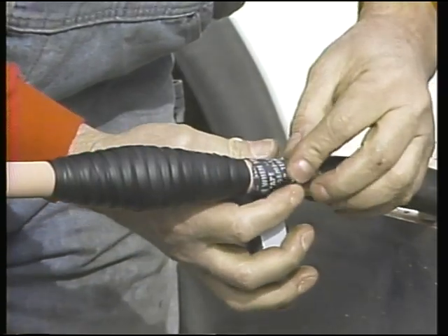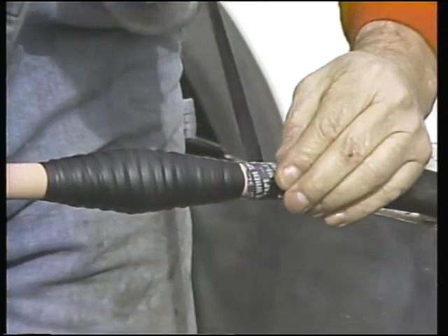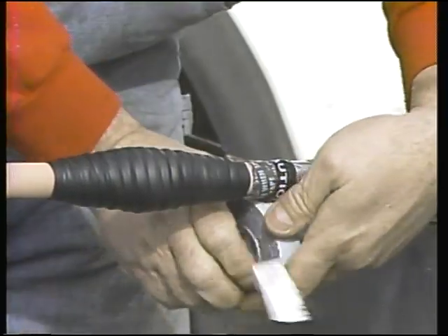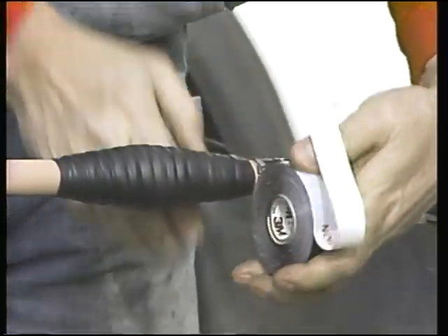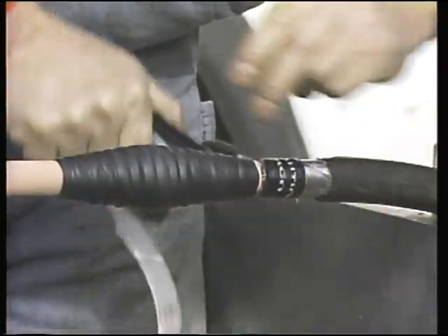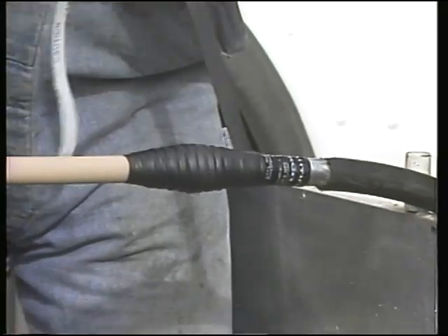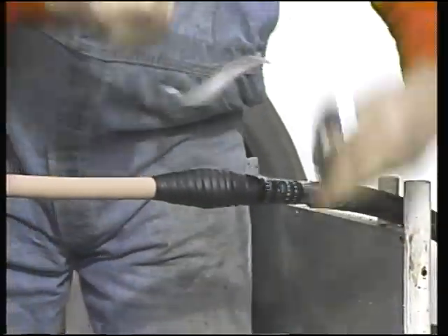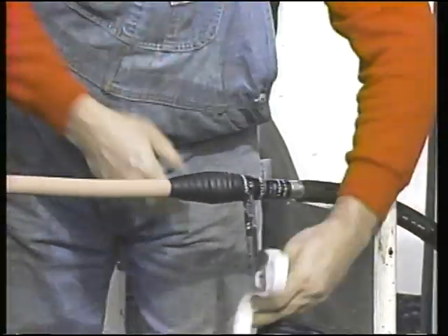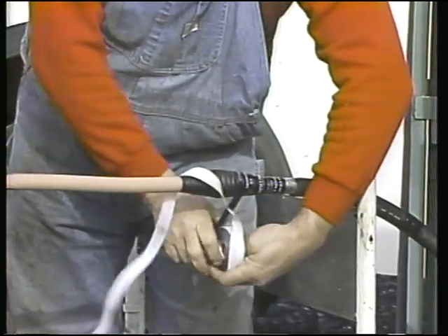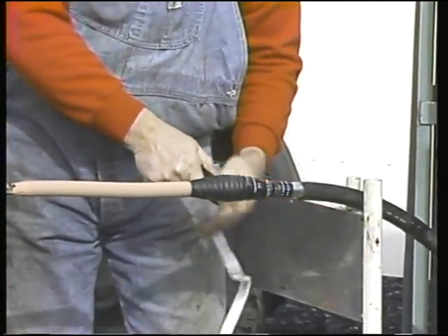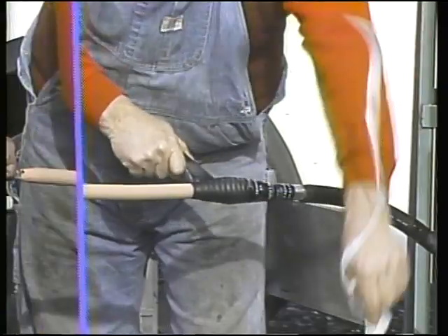When the cone is complete, semiconductive tape is applied to restore the function of the semiconductive insulation shield that was removed. The semiconductive tape is applied using half-lap layers, beginning at the insulation shield and extending to the widest part of the cone. The tape effectively extends the cable's insulation shield over the larger area of the insulation buildup.